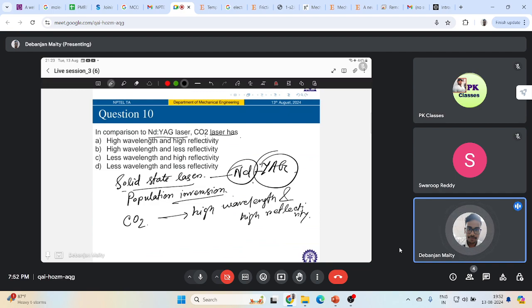So what is the problem in laser beam welding? Very high reflectivity of the laser beam by the metal surface. This is a well-known problem. As much as about 95% of CO2 beam power can be reflected by a polished metal surface. Reflectivity is slightly lower with a YAG laser beam. You can't eliminate those disadvantages, so you have to do something so that it will be reduced.